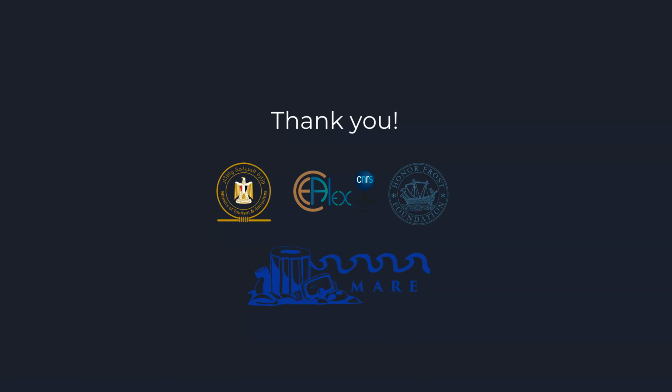And we make sure we take these points on the most stable day, when the sea is very calm. Like I said, the great thing about photogrammetry is that I don't have to take the point before taking the photograph. But it's very important to put the point so that it appears in the photograph. After that, we can take the coordinates anytime later, even after a year, two years, three years. But it's crucial that this point is shown in the photo itself.